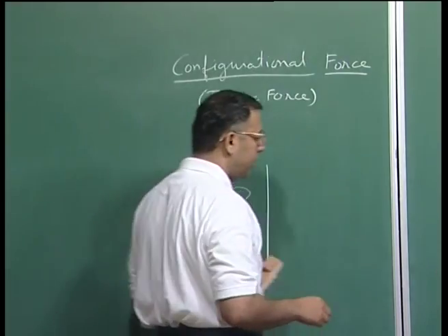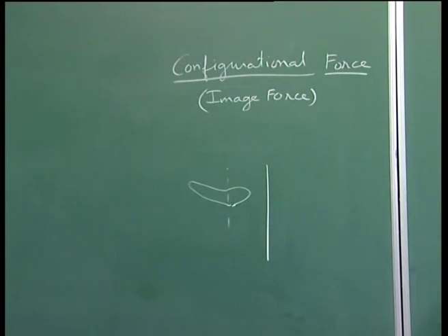So, the image force is a kind of configurational force which attracts dislocations towards free surfaces. Now, as I said, the reason for the attraction is the lowering of the energy of the dislocation as it moves towards the free surface, and finally when it reaches the free surface, it creates a small step and all these stress fields are relieved. On the other hand, suppose I have an interface with a harder material, then that will